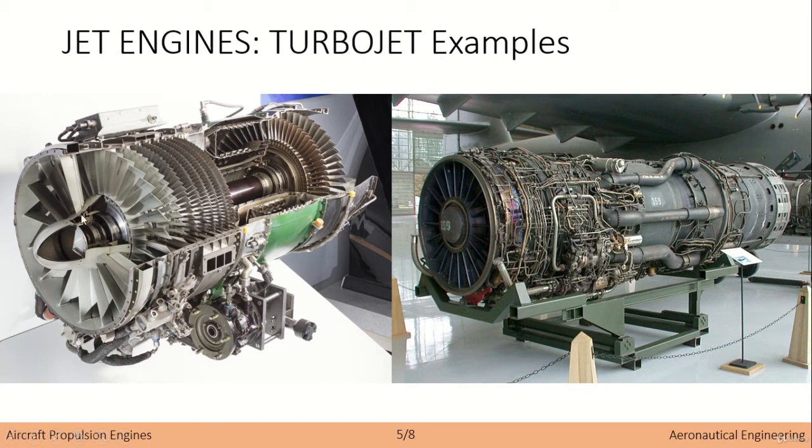So first of all, you see the inlet on this part. You see the different compressor stages, okay. You can also determine that these ones are a bit different than the following ones. In fact, you can see that the airfoils in these cases are quite larger compared to the latter cases, and this is because the pressure in this stage of the engine is actually lower than in these cases.